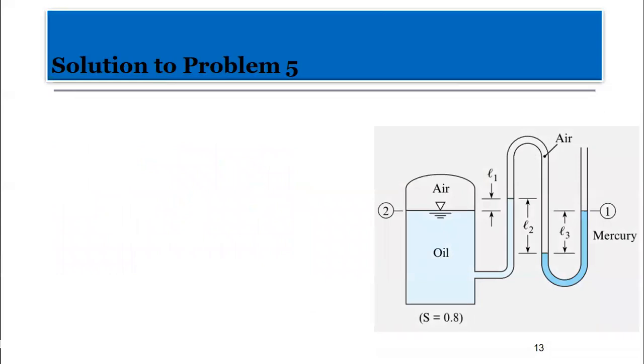With consideration to the diagram, remember, we use the walking-through method where we move through the manometer. As we go through, we take into effect whether going down is positive or negative, whatever option you choose. Remember the general formula.